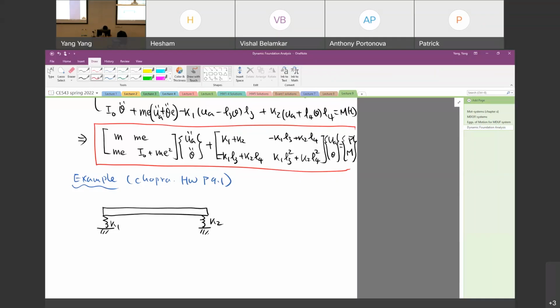The bar is constrained so it can move only vertically in the plane of the paper. Note, this is the system of example 9.2. Formulate the equations of motion with respect to two DOFs defined at the left end of the bar.